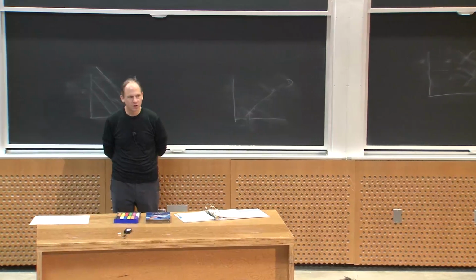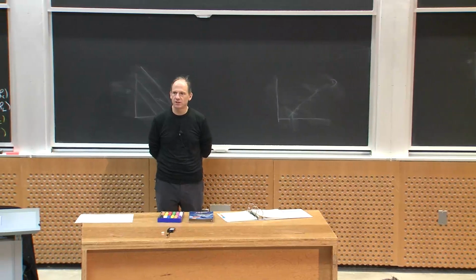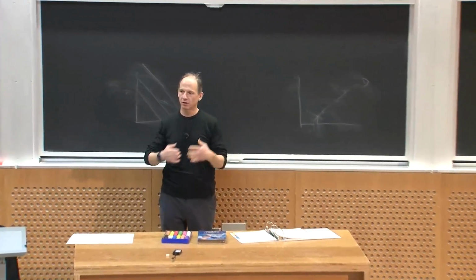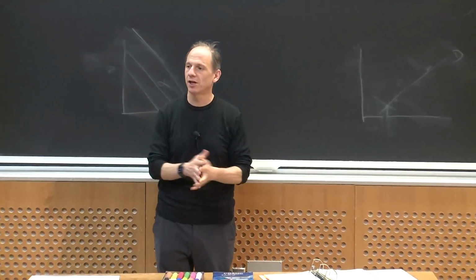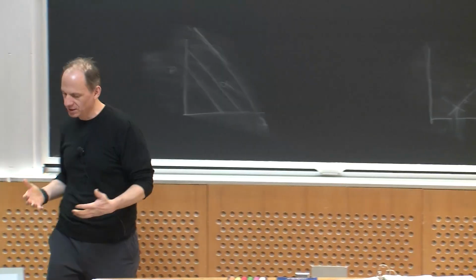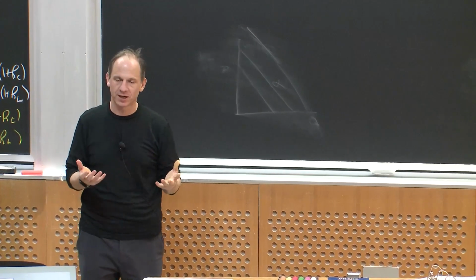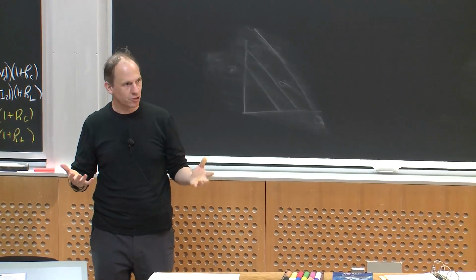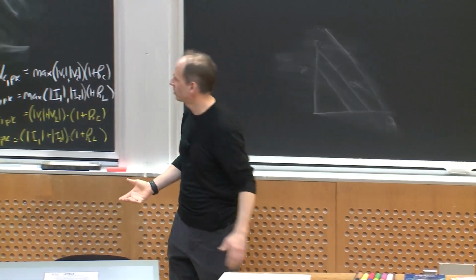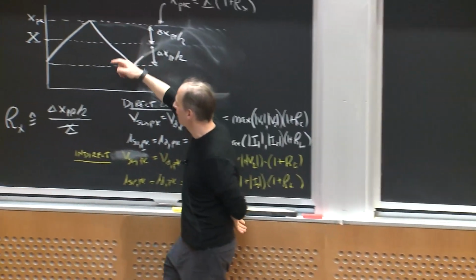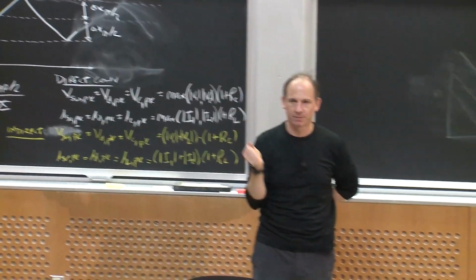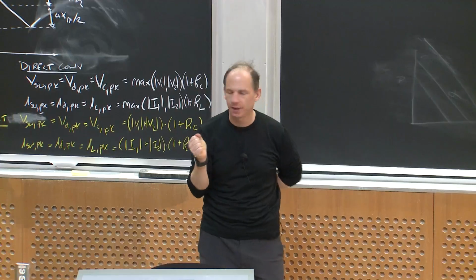So I wanted to keep talking about DC to DC converters today, and keep talking about the impact of ripple and operating modes of DC to DC converters, right? We did some analysis last time, and what we found is that under reasonable approximations, the inductor current waveforms in a PWM DC to DC converter tend to look like some DC value plus some triangular ripple. And the same thing for the capacitor voltage waveforms, okay?